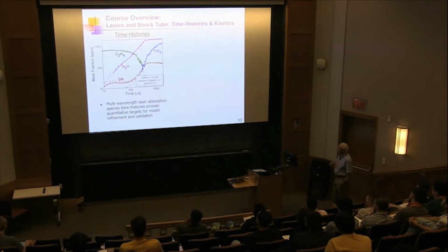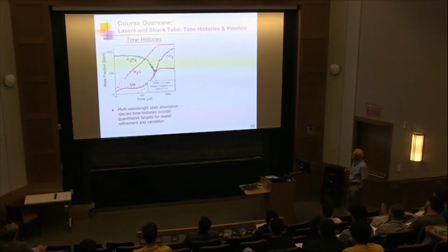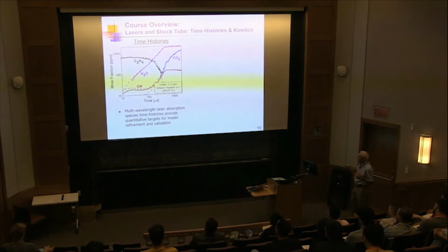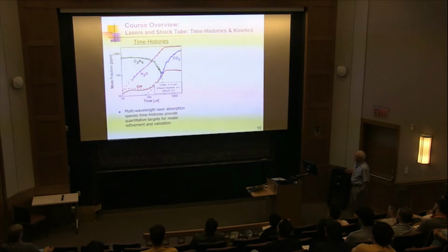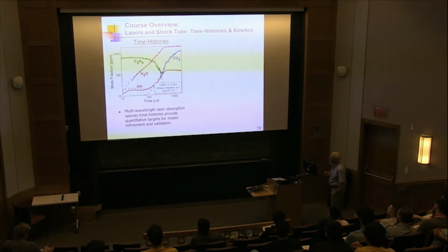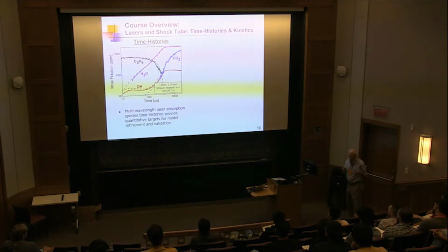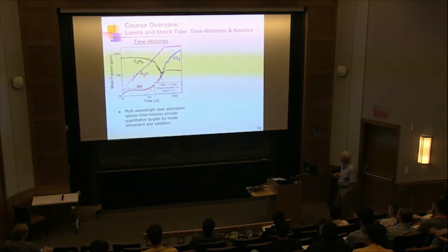This is a case where we shock heated heptane, 300 parts per million, dilute in stoichiometric in air, but dilute in argon, 1500 Kelvin, shown on a logarithmic scale. And so we start with heptane, C7H16. And what we find is that within 10 microseconds, at this condition, most of that heptane, much of it had been converted to ethylene. So big molecules want to be small molecules. Start with a big fuel molecule, it wants to get smaller, it wants to work its way towards combustion products, H2O, CO2. What we observed when we looked at this is a bit of a surprise.